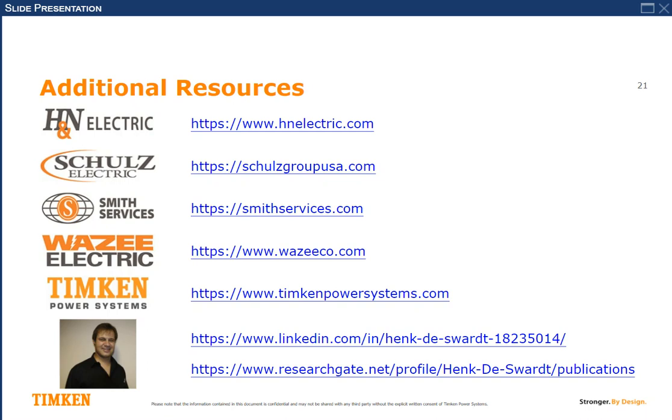it damages the insulation, it ages the insulation. So whether it's a high efficiency or standard efficiency motor, in both cases, I need to make sure that those losses are maintained during the repair. In some cases, if I can reduce them, that's good too, because if I don't, then the machine will not last as long as it should because of the increased temperature, or the machine will cost me more in energy costs. That's why it's important for not just high efficiency motors, but all machines.